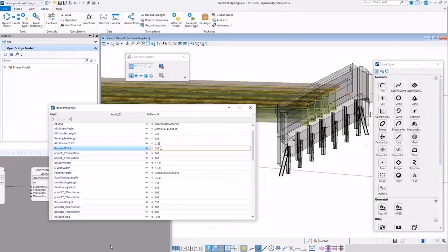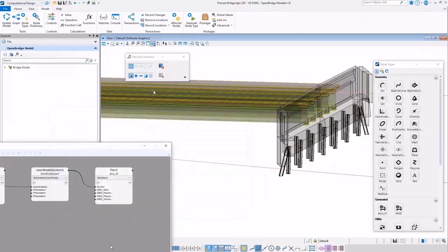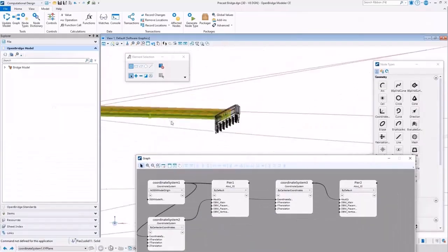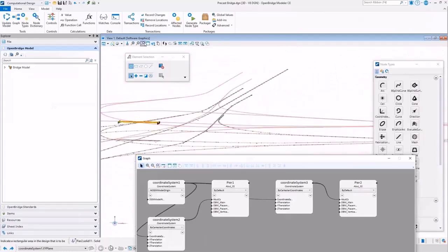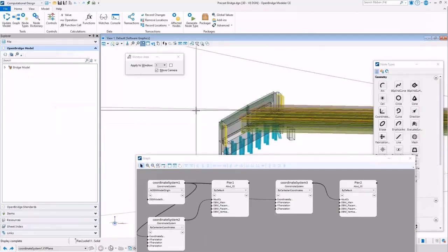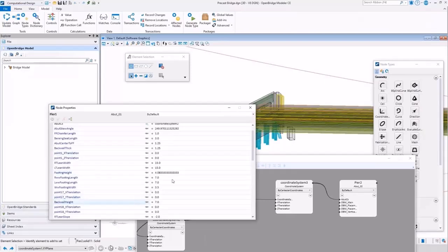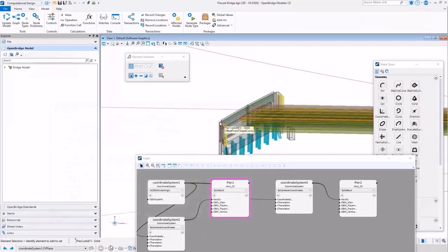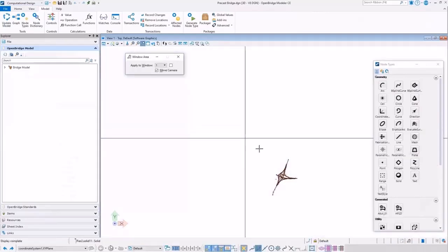And then of course, we're making more efforts. This is a technology preview in order to match variables on the bridge with variables on GC. For example, the width of the deck, right? We want to read the cross slope on the super elevation, so we don't need to enter the super elevation of the abutment itself. We can just read it directly. So on both sides too, or here, for example, oh, I put the pier backwards. So I will just change it, or place it again and recognize all those differences. So I can just modify it on the fly if I need to, right?